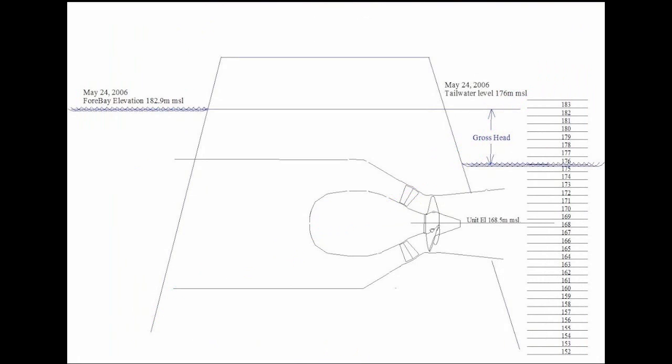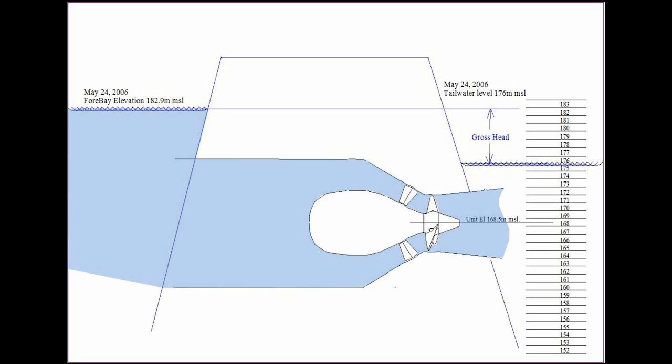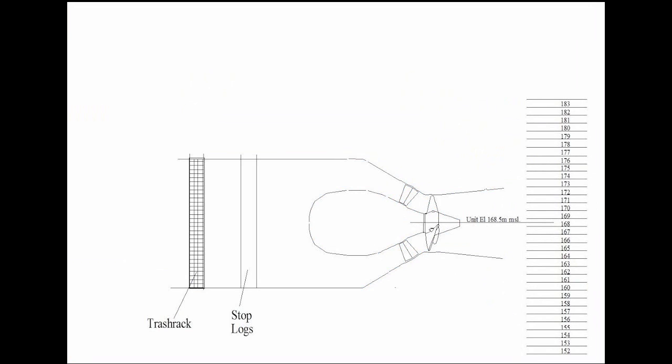Now let's put this into the context of a bulb turbine with a Kaplan runner. The cross-section of the civil works in a 7.5 meter high dam shows a Kaplan bulb turbine and the water passageways constructed to direct the river's flow through the turbines. Although a measurable efficiency decrease is caused by trash racks and stop logs, you've still got to have them.